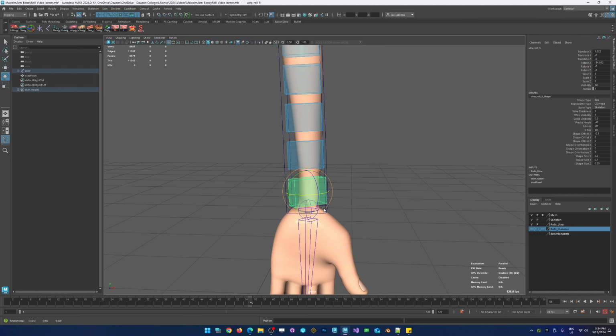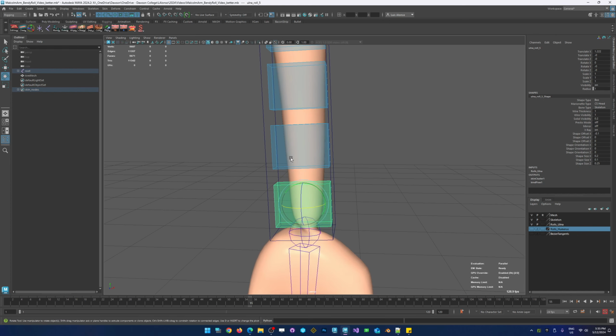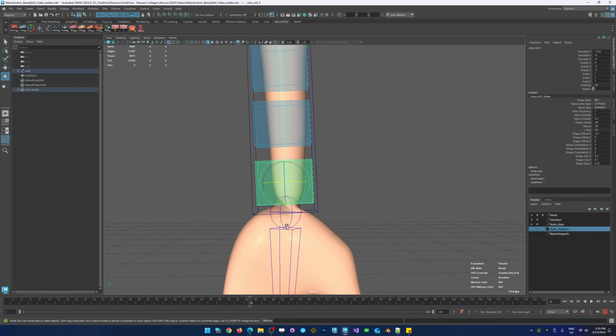It'll explain in great detail, painful detail, how vertex values in a linear skin are done, and how it's calculated, and basically the weaknesses of using linear skinning. So this is a result of using linear skinning. It can cause these kinds of things where you have a full rotation, and all it's doing is linearly blending between the two values, and it can't do anything about it.